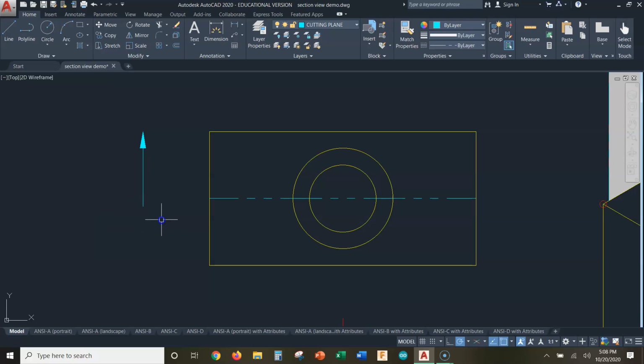All right. So far, so good. Now I want to extend this out there, so I'm going to use the extend command. I'm going to pick this object and extend it out there. And then I'm going to trim that little bit away. So there's my cutting point line.